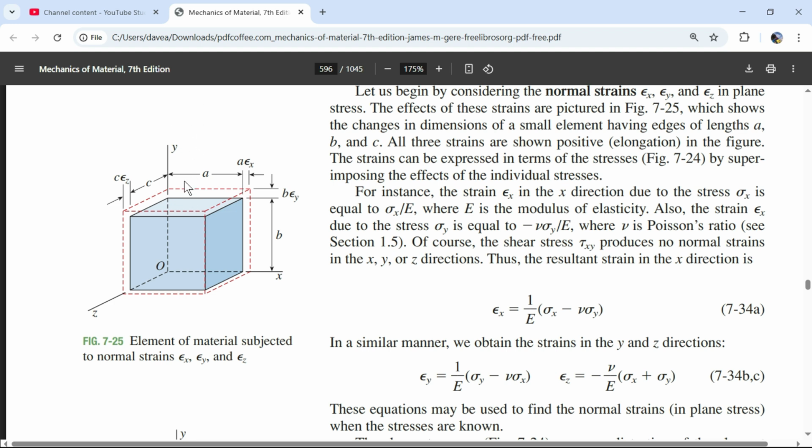So that's Poisson's ratio. If I'm tugging on the y, this is going to get reduced in the x. And this v is that ratio, so it's like 0.3. Let's say that I'm pulling in this direction with 58,000 pounds, and we'll just call it 58,000. We are going to have a stress in this direction due to Poisson's ratio of 0.3. So the stress in the x direction is going to be a negative value, and it's going to be this stress in the y times 0.3. So that's this value right there.